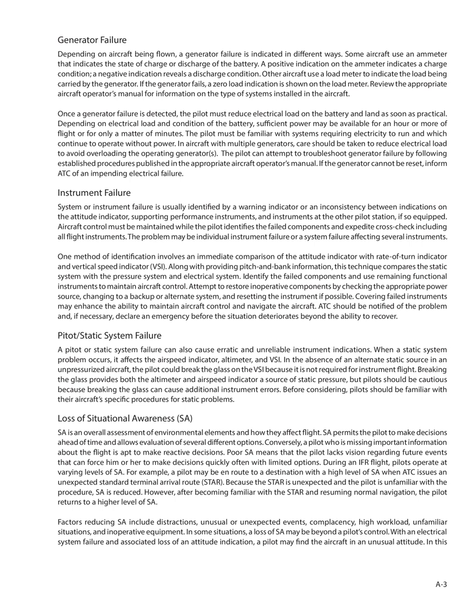In aircraft with multiple generators, care should be taken to reduce electrical load to avoid overloading the operating generators. The pilot can attempt to troubleshoot generator failure by following established procedures published in the appropriate aircraft operator's manual. If the generator cannot be reset, inform ATC of an impending electrical failure.